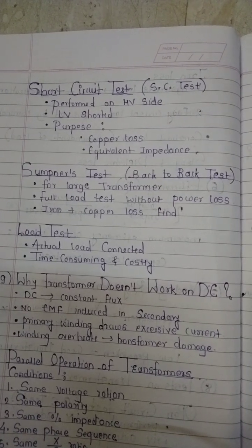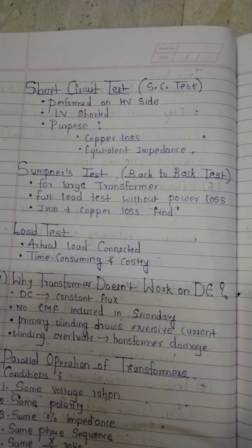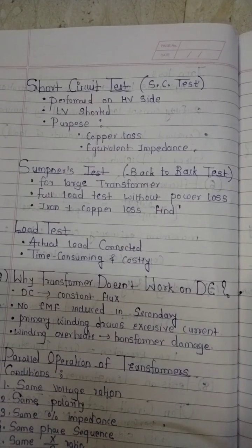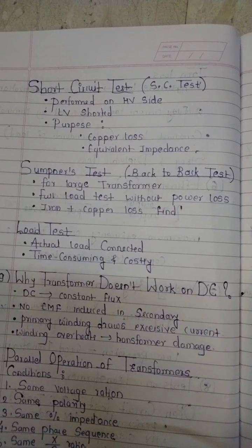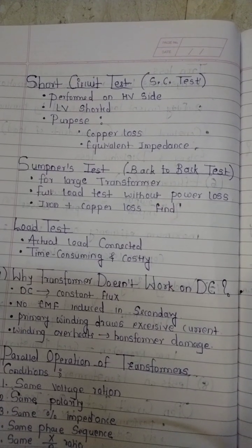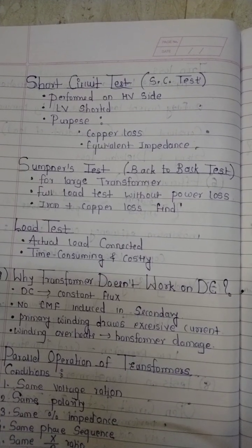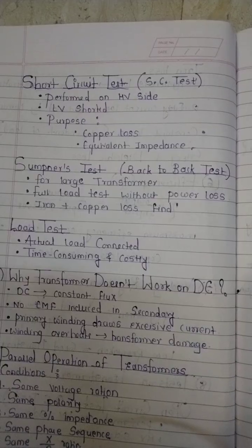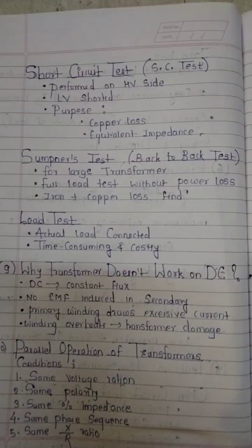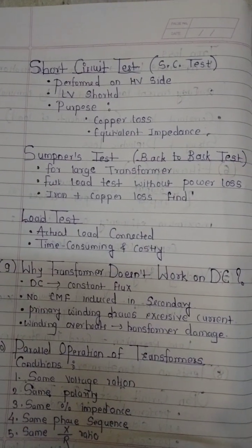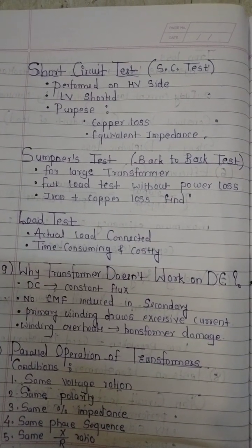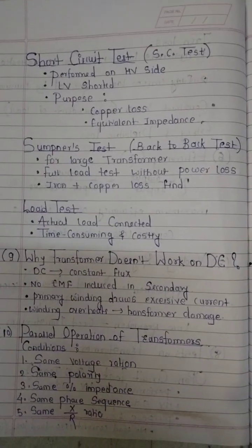What is Sumpner's test? It means back to back test. It is used for large transformers, for a full load test without power loss. Okay, here we are finding the iron plus copper loss. What is load test? The actual load is connected; it is time consuming and costly.